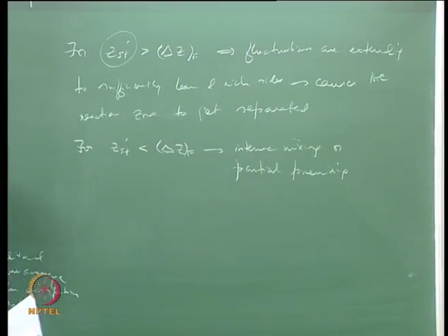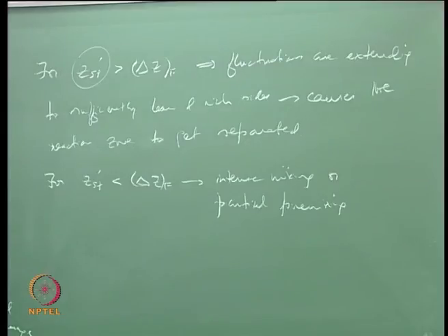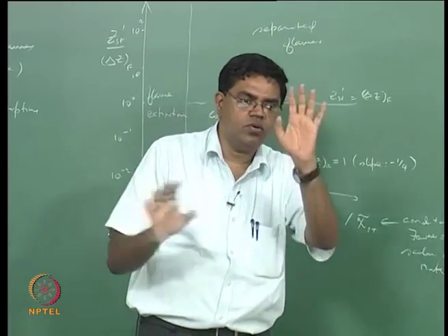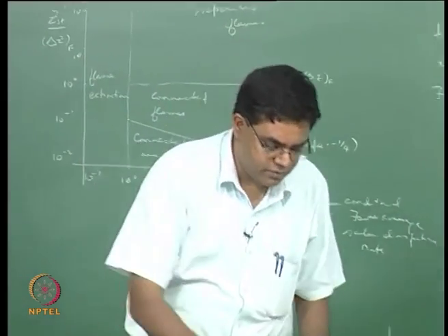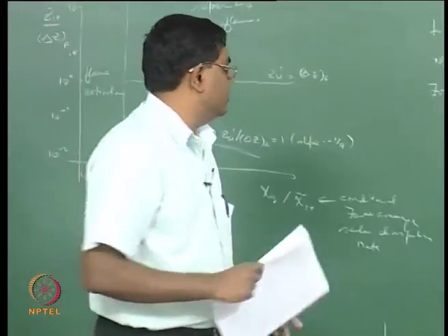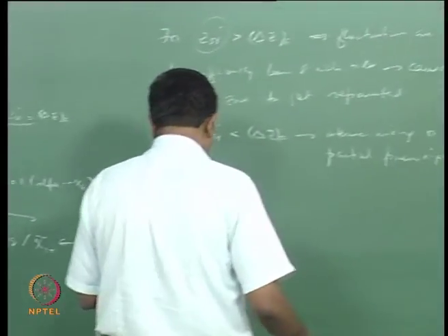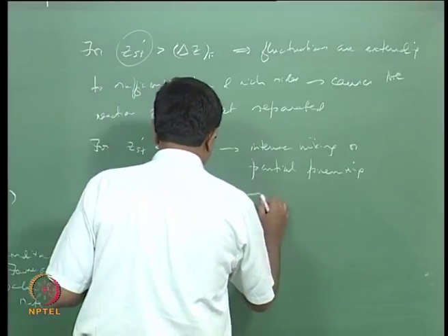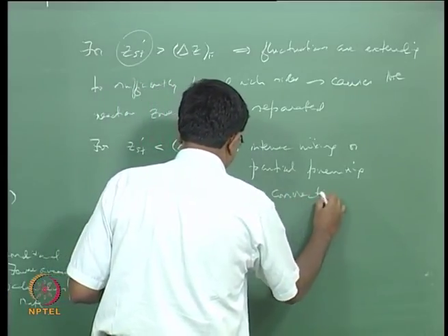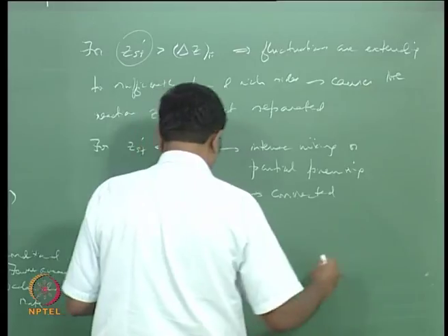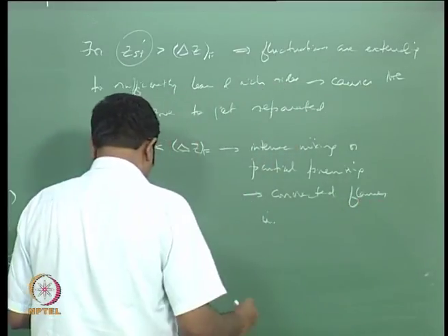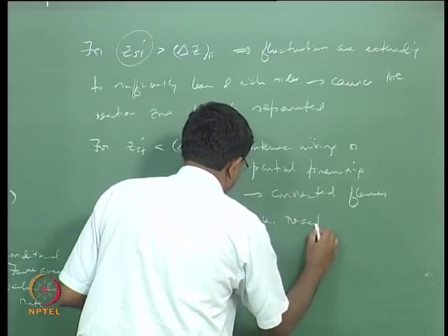So what this means is you can have the reaction zone move around without really getting disconnected, but you will have the preheat zone sense the fluctuations. So effectively you don't really have disconnected reaction zones. So this is essentially connected flames, that is, reaction zones are connected.